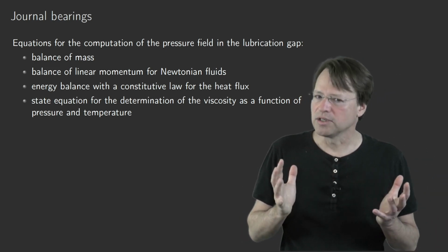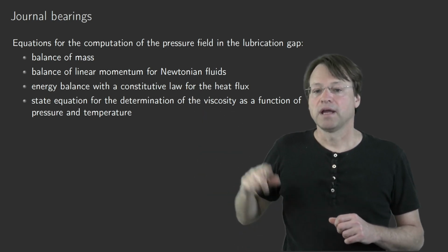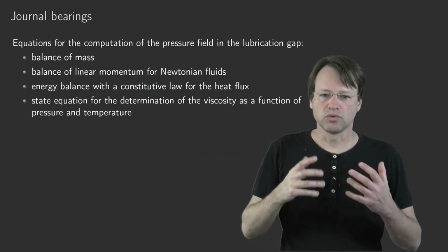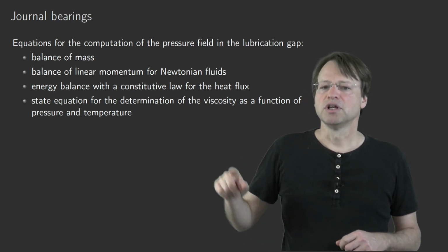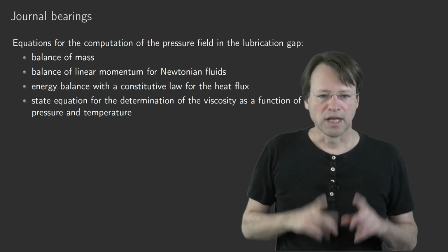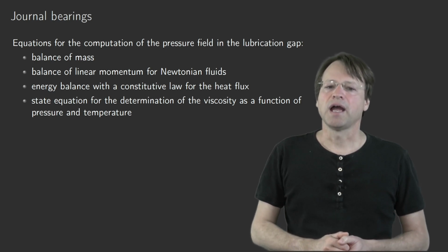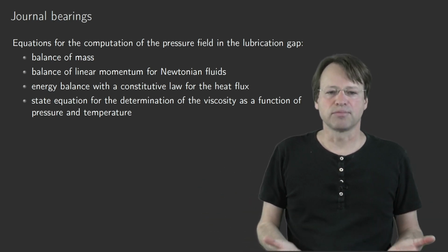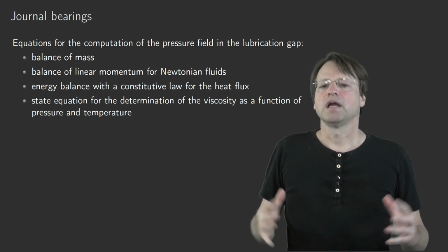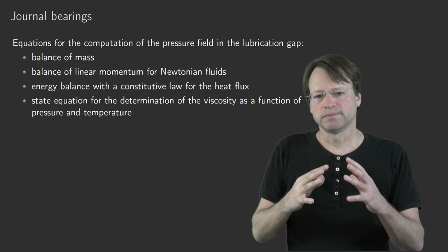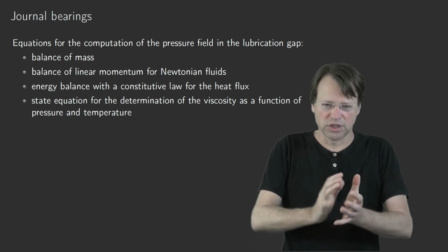The viscosity clearly is temperature dependent. Therefore, we need the energy balance, and therefore we need that state equation in order to, from the energy balance, infer the temperature field. And from the temperature, we would be able to compute the viscosity. On the other hand, the viscosity is also pressure dependent. And what happens? If you increase the temperature, then the viscosity drops down. If, however, you increase the pressure, you increase the viscosity because you press your oil.